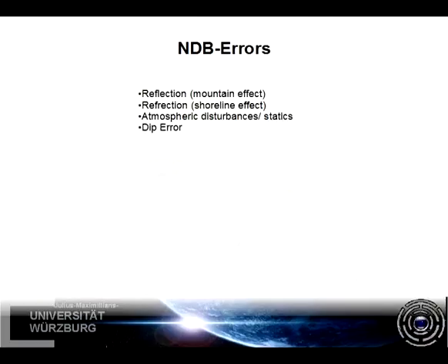A dip error that is equivalent to the correspondent error of the magnetic compass is also an issue of the ADF. The closer the aircraft is to the station, the greater is the angle at which the NDB signal is received in relation to the aircraft's horizontal plane. This angle causes the same problem for the ADF as the magnetic dip for the magnetic compass when the aircraft is banked. Part of the vertical component of the signal is sensed and distorts the indication.